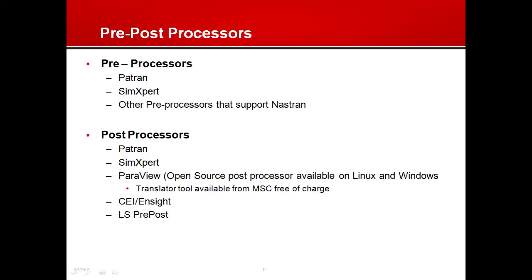Post-processors, there's quite a few available to you. Again, our standard tools, Dytran and SimExpert, are available to you and do post-process. So those are available, but then there's some other shareware. Aero uses shareware, free code, that does a nice job for presentation. CEI Insight is an extremely powerful tool and does fantastic presentations. We use it quite often. And LS Pre-Post, which is a post-processor created by LSTC, makers of LS-Dyna.